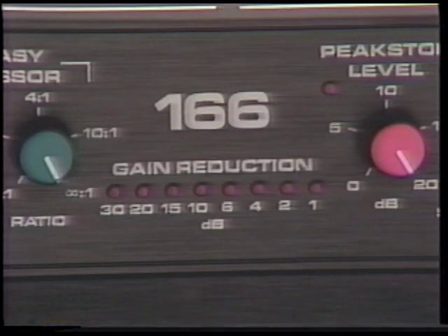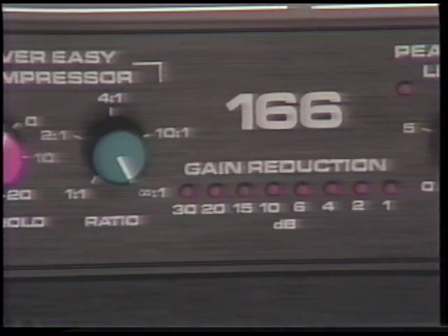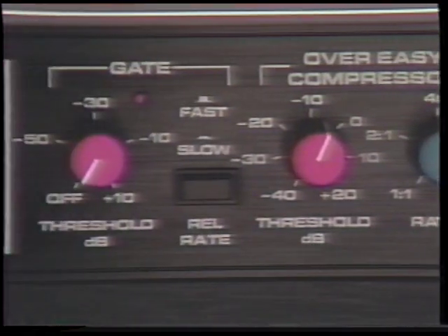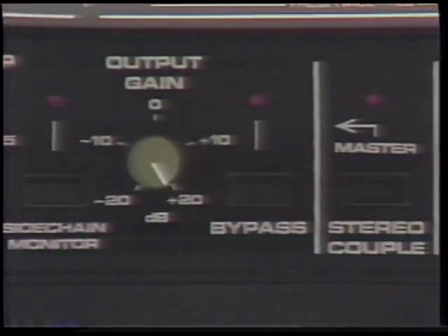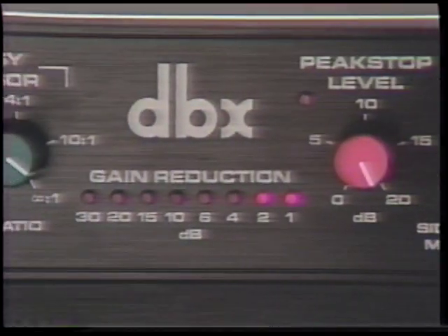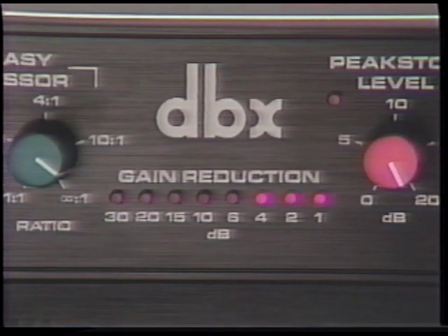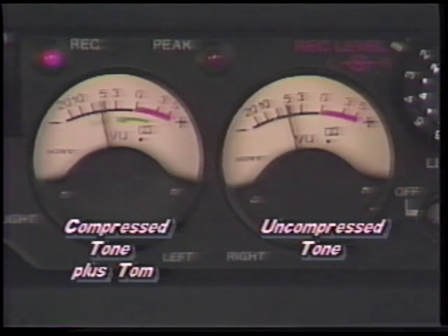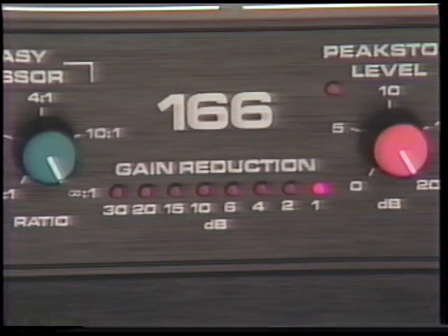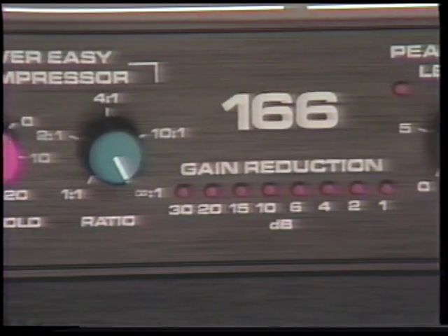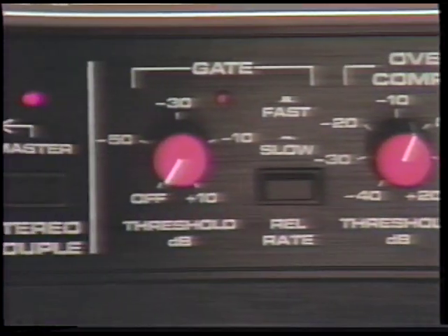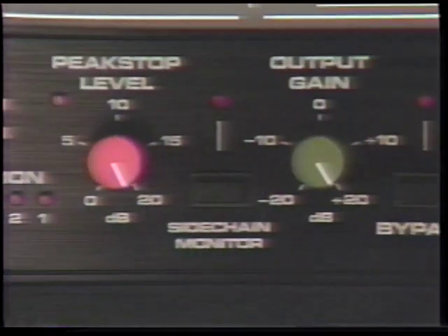We're running this low-frequency tone through two identical compressors which are capable of being interlocked stereophonically. When I trigger a loud tom-tom to occur on the left side, the left output is reduced. If you're listening in stereo, the tone, or any center channel program, will appear to shift to the right. Now I'm turning on the stereo interlock. Both meters are reduced by the same amount when I strike the tom, and the center doesn't shift.